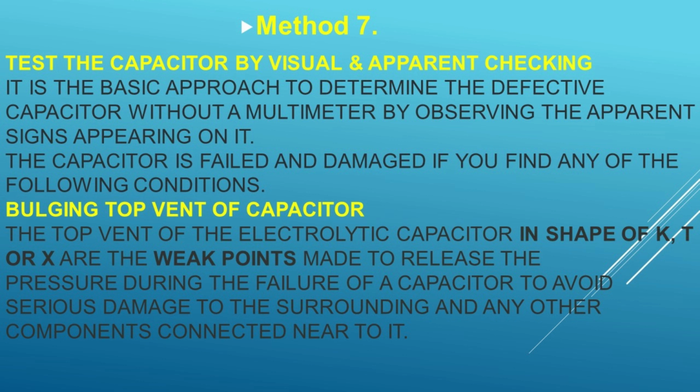Now compare the calculated value of capacitance with the value printed on the capacitor. If they are the same or nearly equal, the capacitor is in good condition. If you find a noticeable difference in both values, it is time to change the capacitor as it is not functioning well.